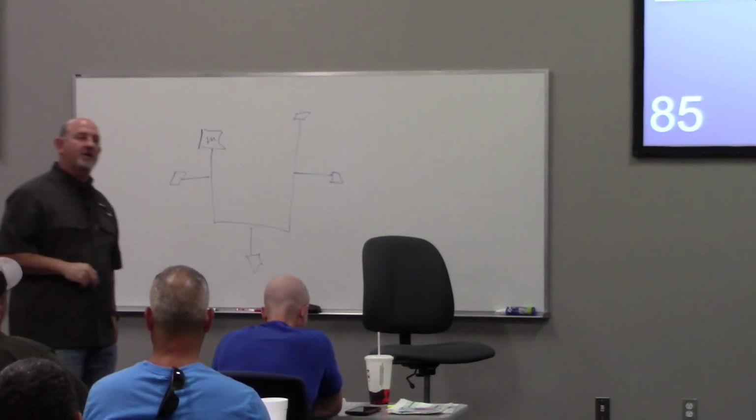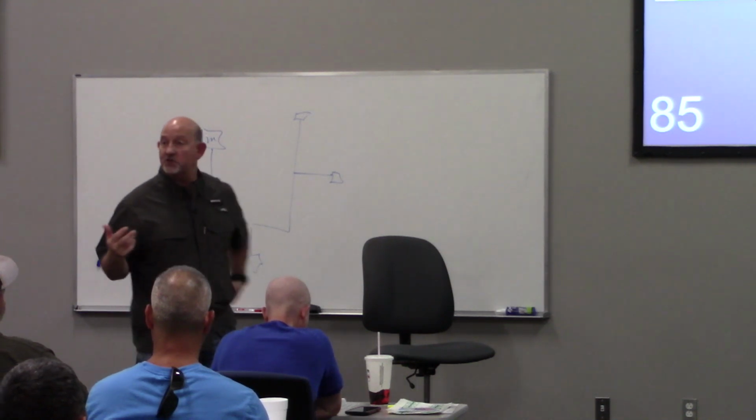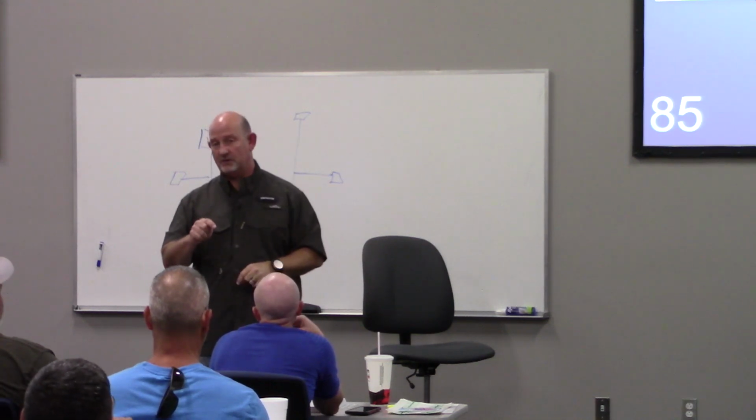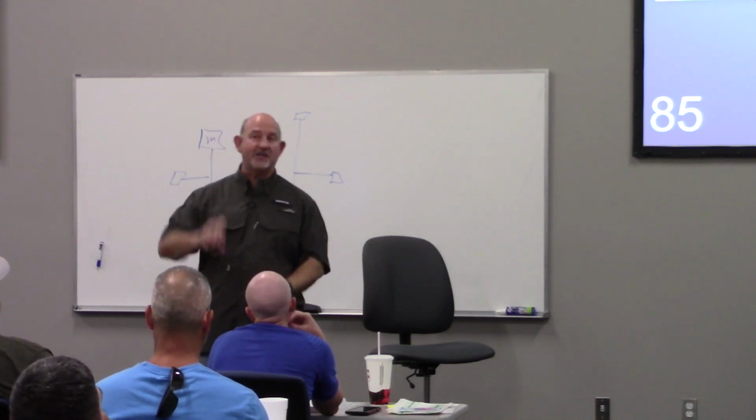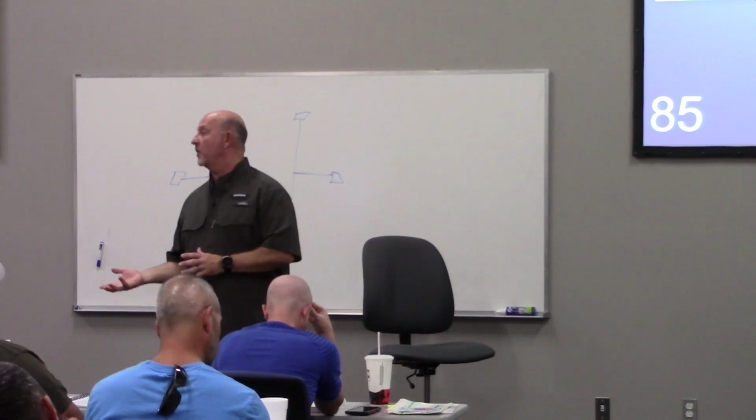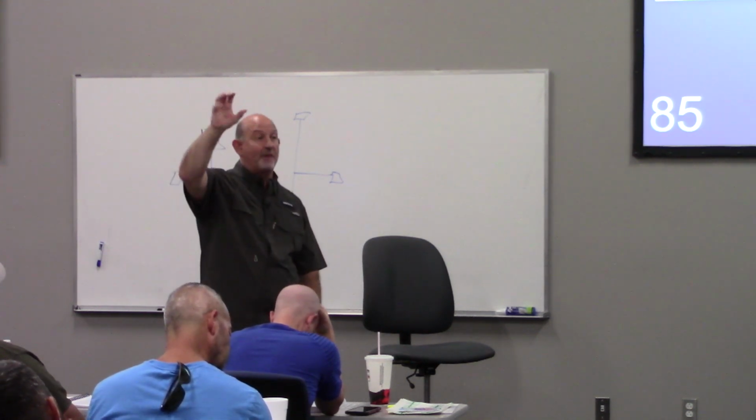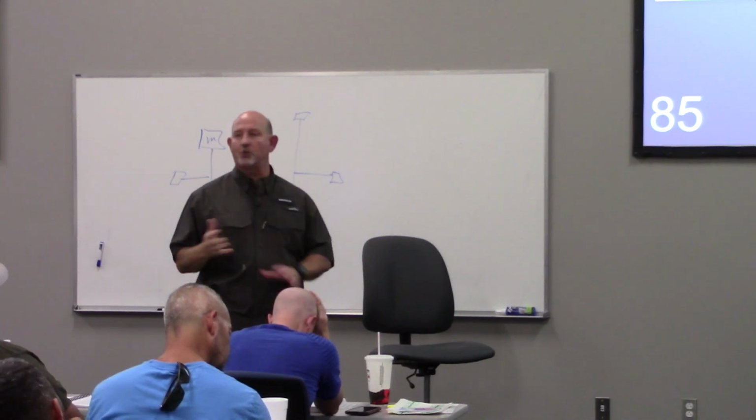Now the other mistake people make is, let's use our 350 square inch example. The next mistake people make is they divide it by 2. That's 175 square inches. 175 in the top, 175 in the bottom. Do you agree that second sentence, first word said each opening? That means I need 350 in the top if I need 350, and I need another 350 in the bottom if I need 350. Or if the 100 square inch would meet both rules, I need 100 in the top and I need another 100 in the bottom. Each opening has to be that big.